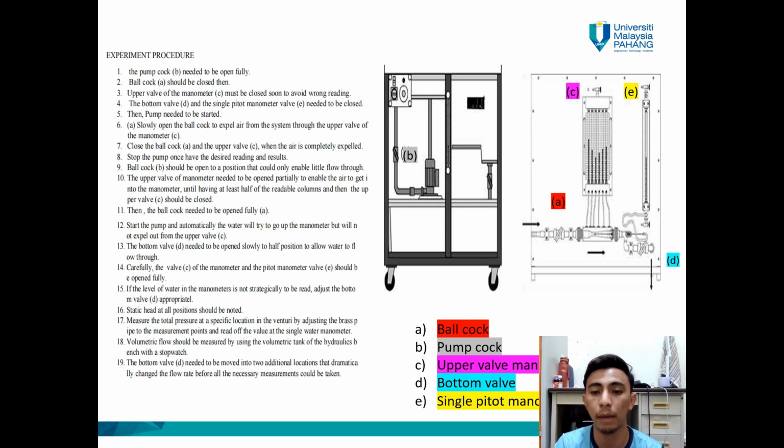After that, we can start the pump. After we start the pump, open A slowly to expel air in the manometer, then close it back when the air is completely expelled. Then we can stop the pump once we have the desired reading and result.